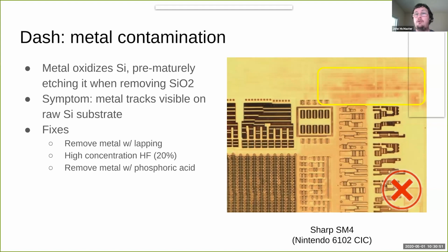And if you look in failure analysis books, they recommend a 20% solution as a compromise because, safety aside, a 50% solution eats things so quickly that although it does eat the things that you want to eat quicker than a 20% solution, it'll also start to react quicker than you can react. So 20% is a good compromise to get good results.